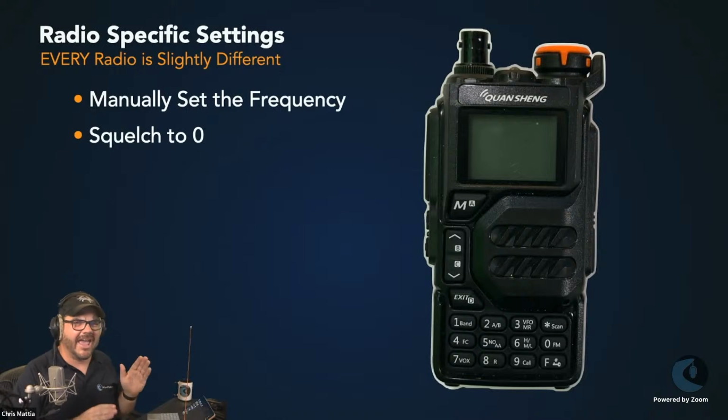A lot of people are like, hey, but I don't want to listen to the noise, or I didn't really know that was what you need to do. So when you set the squelch all the way to 0, you're not filtering out any audio, because remember how squelch works: squelch is listening for an audio signal to come in at a particular level. Well, if you're talking to a gateway that's a pretty far way away and you just barely have a connection to it, it may not be enough to break the squelch.